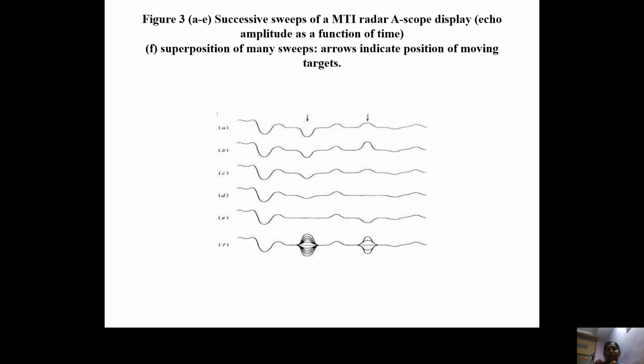If you observe the voltage of each sweep, in this portion, this portion and this portion the voltage does not vary. There is no change in the voltage because they are signals received from the clutter, and there is no frequency shift in them. So V difference is constant, taking a value from plus amplitude A4 to minus amplitude A4.